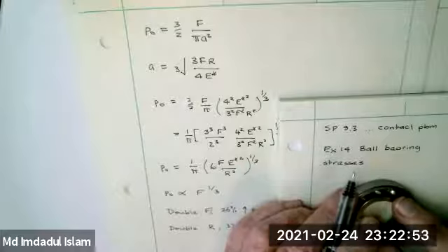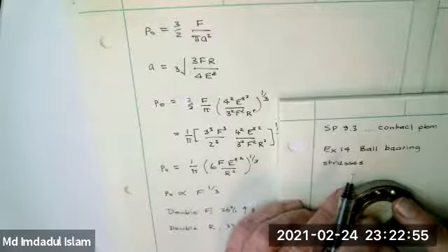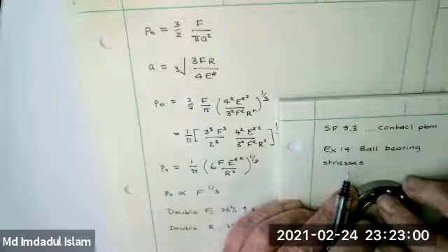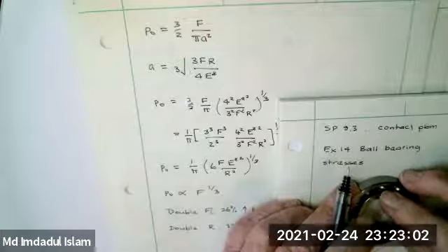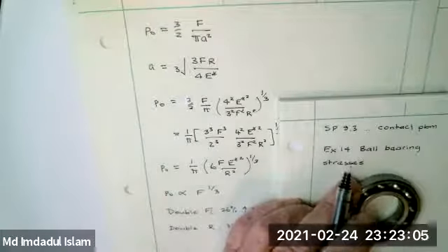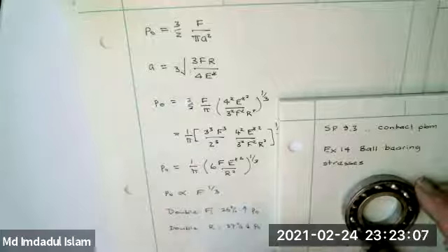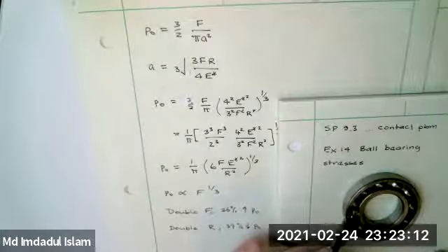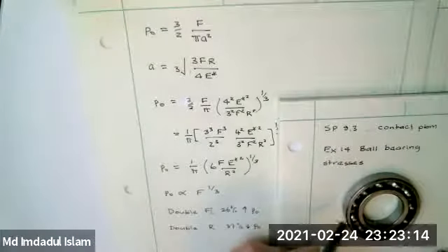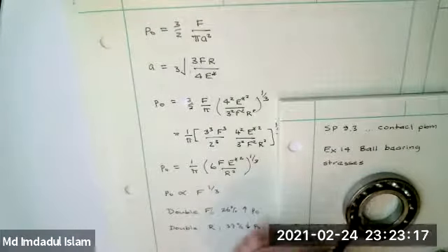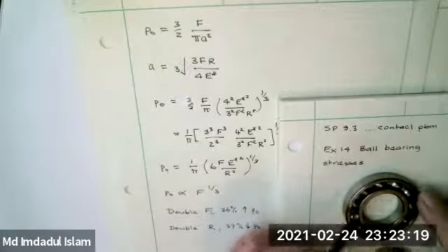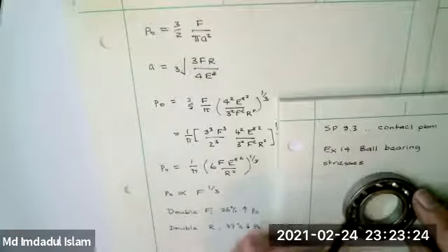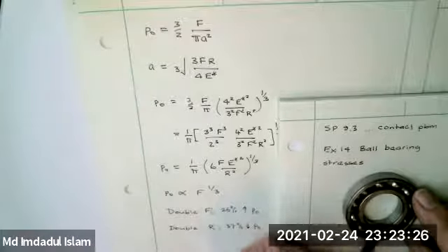And I think that roller bearing I had a lot more slipping. This thing doesn't seem to be slipping at all. And so when I turn this, let me get my hands out of the way. I can see the mark quite clearly, but you can't. It's come down to the bottom. This is almost at 9 o'clock now, and that's about what you'd expect. With that roller bearing, it wasn't moving as far as that because there was more slipping. I could see there was more slipping. Without slipping, its velocity would be half, and it's got a slightly bigger radius, so it doesn't quite get to 9 o'clock when you get to 6 o'clock.